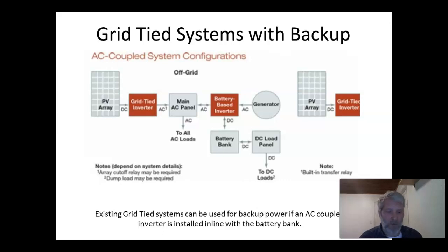Could have your TV on it, but it may take off things like having your shop connected where you're going to be pulling 60 amps. Unless you own a wood shop and that's how you make your money, then that could be essential to you. But for most people, you can eliminate probably 2/3 of everyone's electrical needs, based on just what they actually need. What that does for you is it allows you to create a smaller battery bank, which saves you a lot more money if you're not powering the whole house all the time, or at least having to power the whole house at the same time.